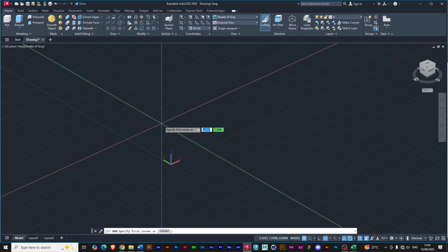So this is for the X, that is for the Y coordinates. Remember, just the same way we've been doing everything. The first number is what it will represent. Your first point, XY, then your second point, XY, generally. So to activate it, what you do is you have a measurement. When you type the first number, you separate it by a comma. Once you use a comma, it jumps to the next grid. If you use an @ sign, it will give you a specific point on the grid.